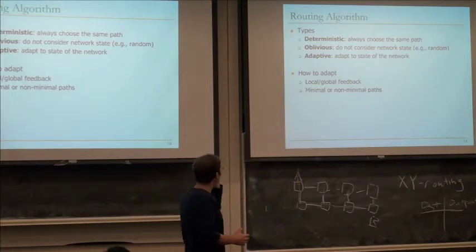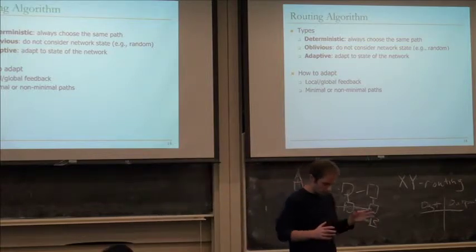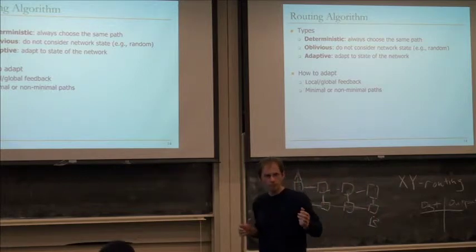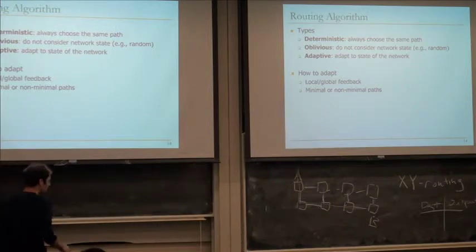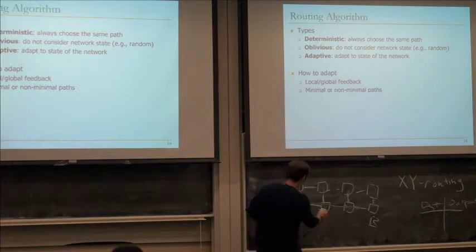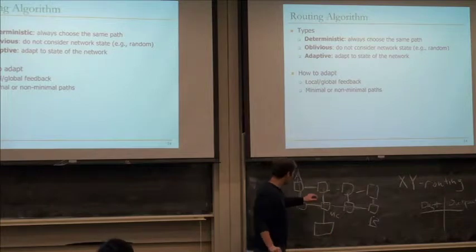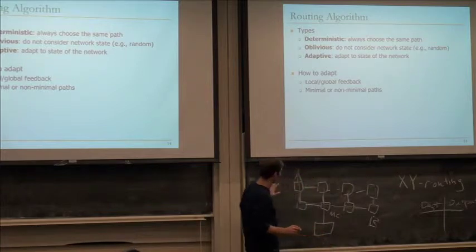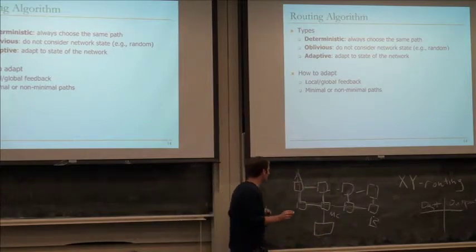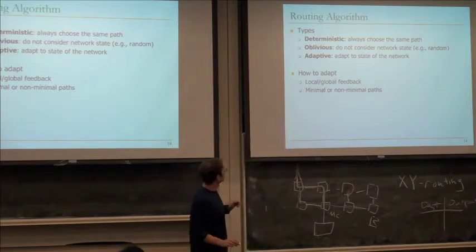balancing, right? So there's another option here, which is that say I have a network where some routes are or can be more loaded than others, right? Say that in this mesh, I sometimes get hotspots where maybe this is a memory controller here. So maybe this connects to DRAM, and a lot of traffic often comes here. If I just have a deterministic XY algorithm, or any deterministic algorithm, maybe there are some nodes that are talking to the memory controller, and they'll congest certain paths, right?